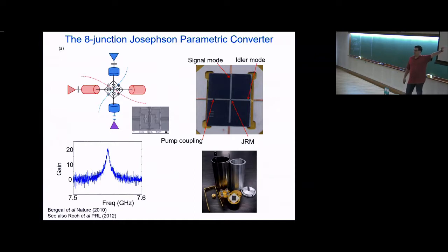So you'll see in very much of the literature, this 20 dB number. It's not because it's special or given by physics, it just turns out, depending on the kind of amplifiers we can buy to follow this thing and losses in cables and stuff like this, it's just a very convenient number. If you wanted 18 dB or 37 dB, you would just program it up. Okay, so that's the superconducting amplifier.